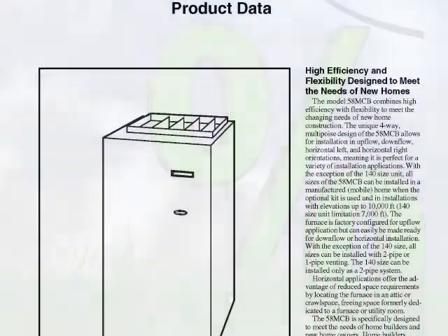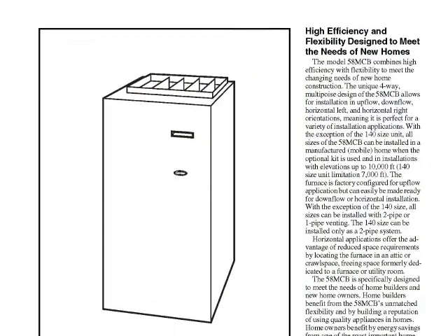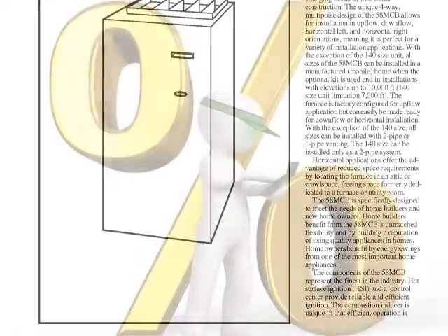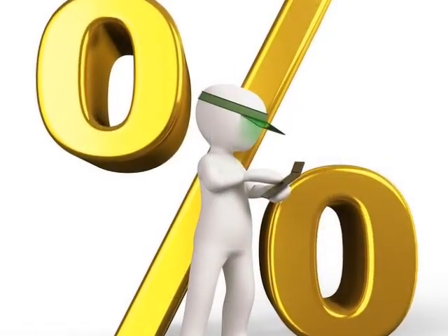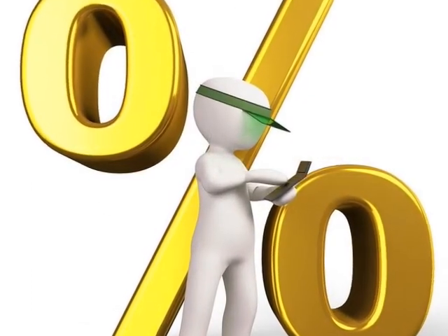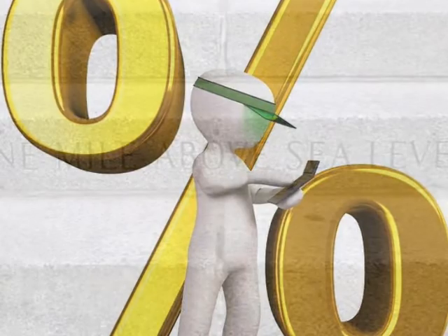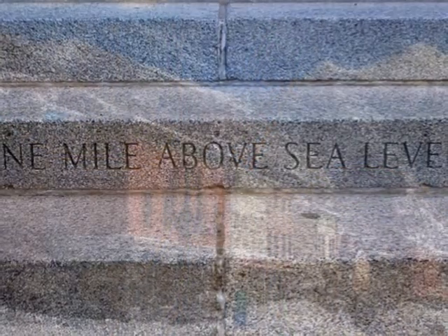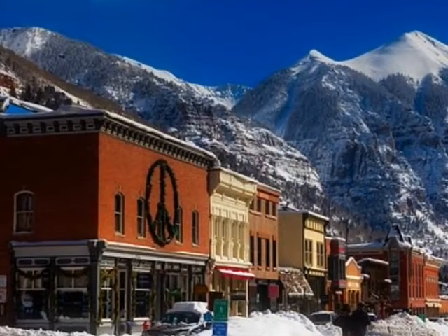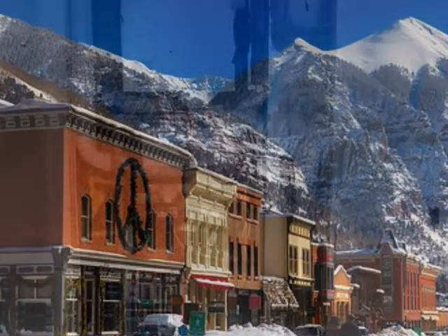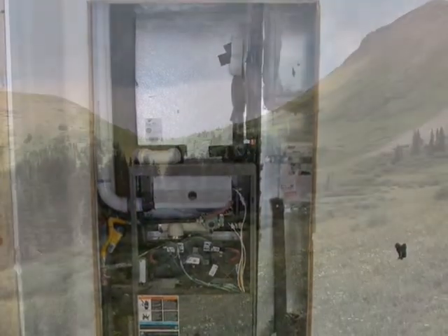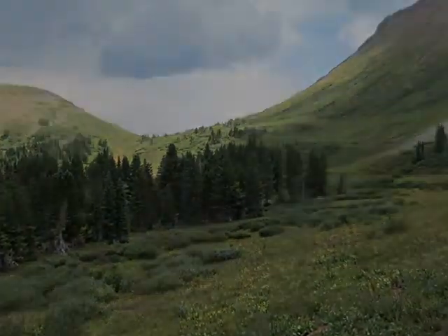This is why we need to have the manufacturer's performance data provided to us. Is it 2% per 1,000? Is it 4% per 1,000? Because we want to make certain that the output rating of the appliance works whether it's at 5,000 feet or 10,000 feet above sea level. That's a critical piece. Make sure that they've not only rated for efficiency, but also for altitude.